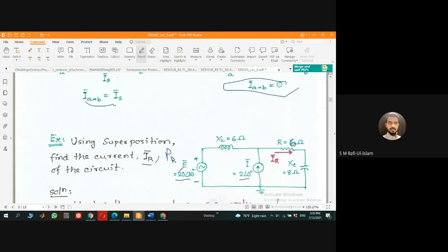The answer is this. Since it's a phasor, the sinusoidal value we have learned is E equal to 20 root 2, because it's the peak value, then sine of omega t, meaning 2 pi f, plus 30 degrees.